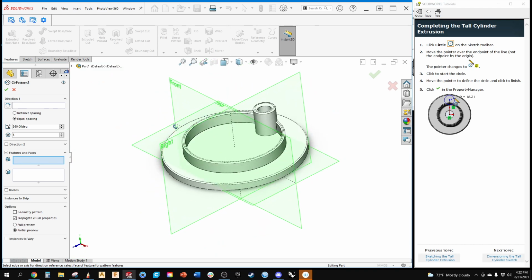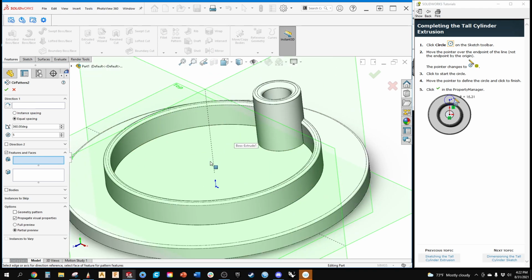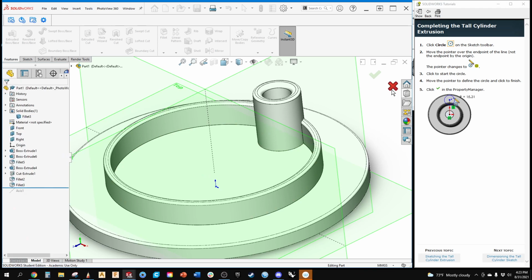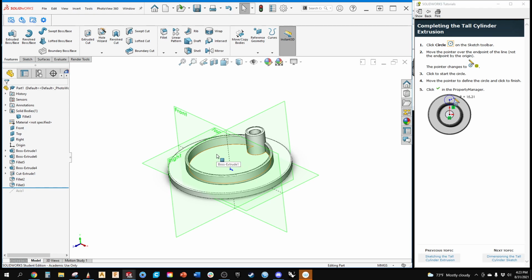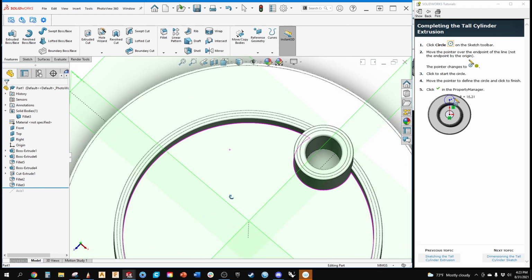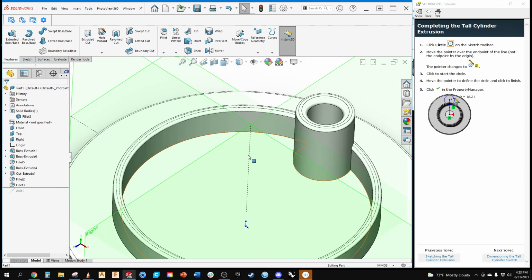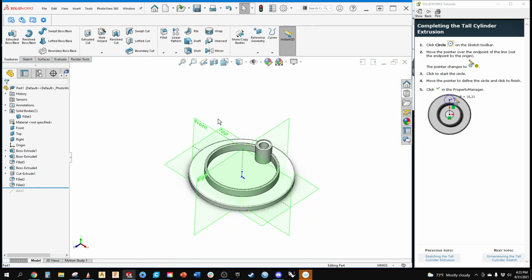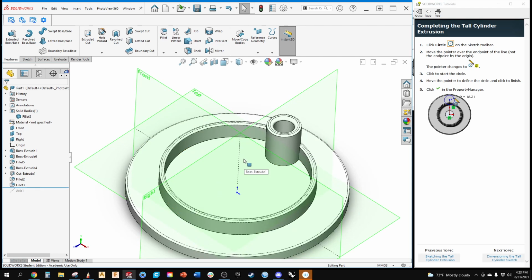Well, I don't really have anything. There's nothing I can click. I can click the origin, but it's looking for a center axis. What I want to do is create a center axis around this object, which would be where you see this dotted line, which is the complete intersection of the front and right plane. This is also why I like to work at the origin.